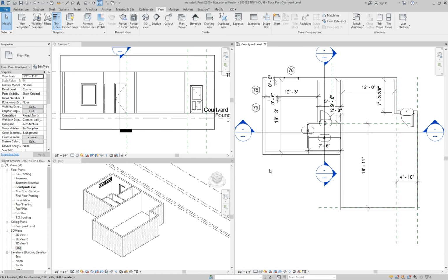at your sketch tools, you can do curves, circles, you can grab lines, what's called reference lines. Whatever you do, you need to draw. But the fundamental thing is wherever you start, that's where you have to end, okay? So start point has to be the same as end point. The other thing that's important is whatever shape you make, you can only have one line or one segment.